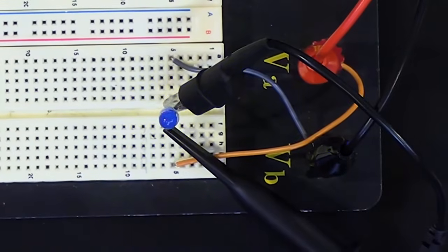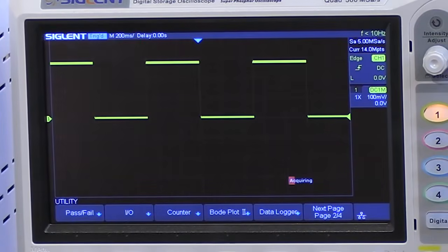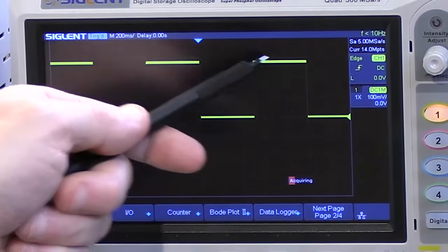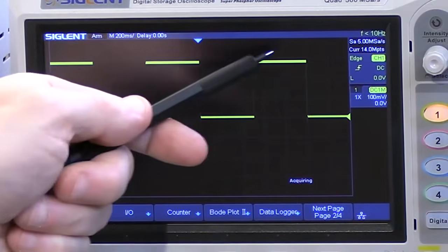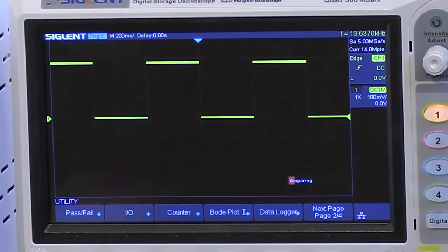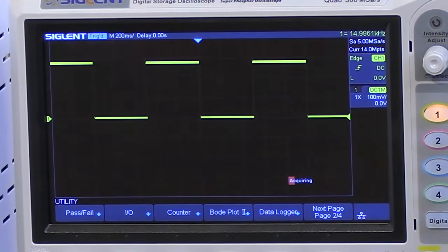We turn the output on and we see that this thing is now blinking, right? And we look on the top display and this oscilloscope is showing the voltage across this diode in real time. So this right here is the 0.0 volts. The top little hats up here are, I think I set it to 2 or 3 volts. Actually, I can read down here. It says 3 volts. So I'm driving at 3 volts, and then 0, and then up and then down. So it's turning on, off, on, off.